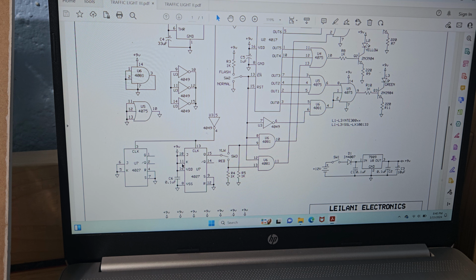When it sees a clock pulse, it'll flop. Now Q is low and not Q is high. And it'll just keep doing that every clock pulse. So I took the output of the JK into the second switch, which I showed you. Now this clock pulse is feeding this AND gate. Remember, this one is high. So now when this high goes into the AND gate, this goes high.